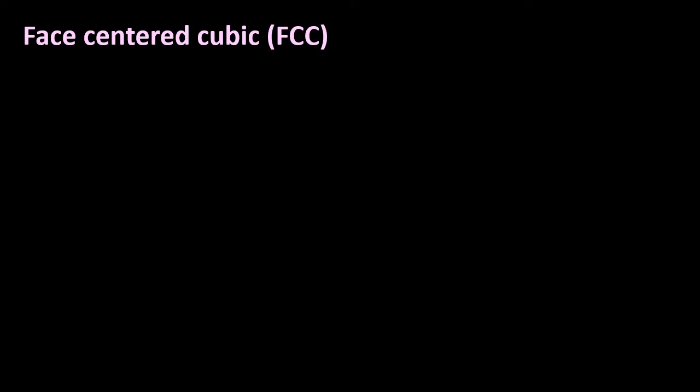Dear students, in this lecture we will discuss metallic crystal structures. First of all, we will discuss the face-centered cubic, or FCC, metallic crystal structure. As we know, the crystal structure formed for many metals has a unit cell of cubic geometry with atoms